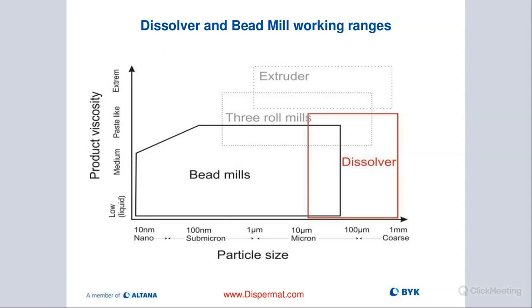We had one customer for specific ink formulations. They were doing everything on a 3-roll mill. They were milling for 18 hours on 3 different pigments to bring down the particle size. And by changing it over to a bead mill, to a basket mill in that case, we were able to do that whole job in 45 minutes. So you can imagine the excitement there and the amount of cost savings just by changing the process is really, really huge when it's done the right way.